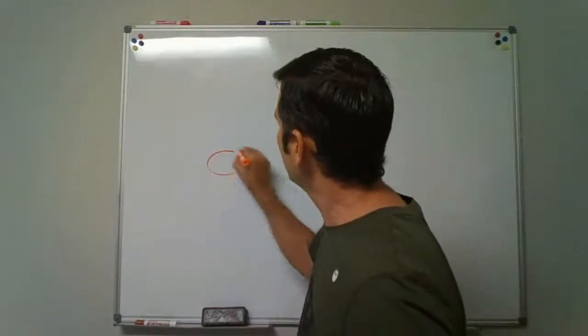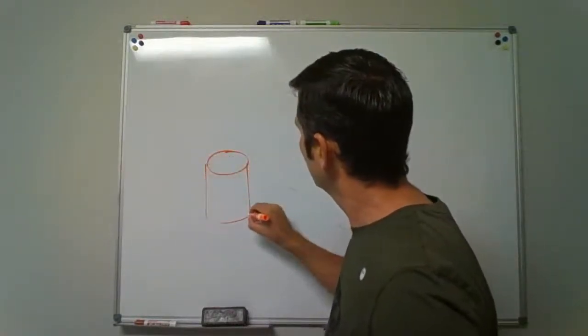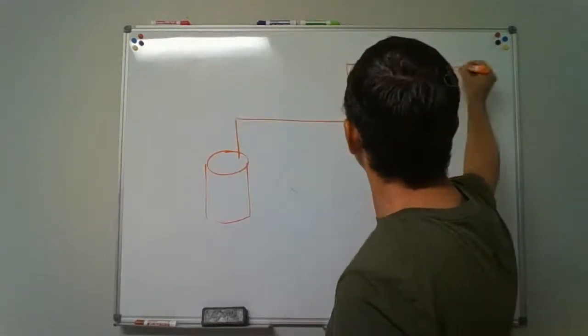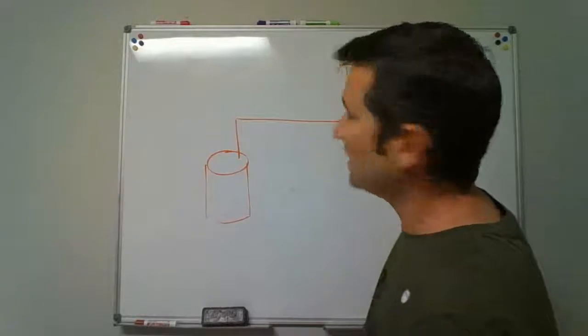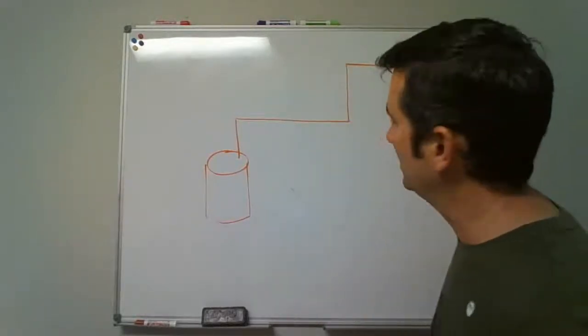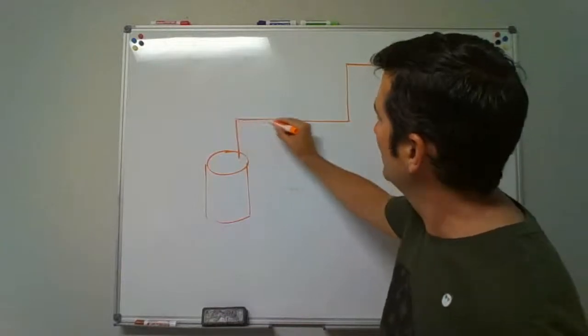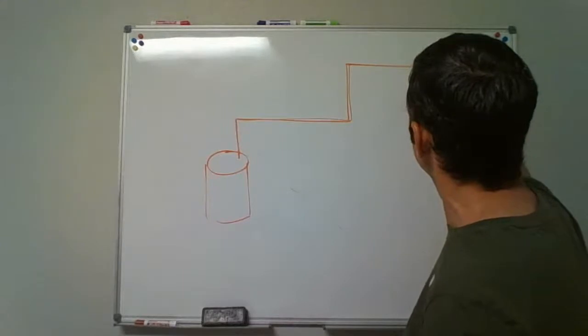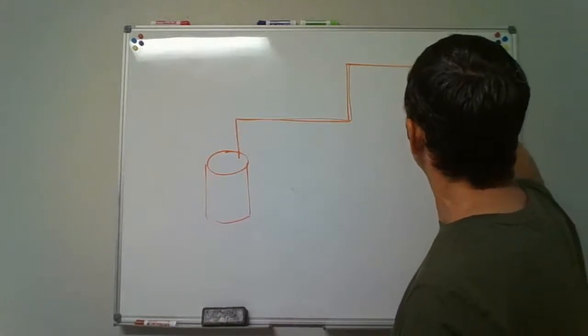So if you're putting in a water heater, you've got to measure it. How do you measure this? It goes along the center line of the pipe and fittings. That term is called developed length. You measure up and over along the center line to a maximum of 50 feet.